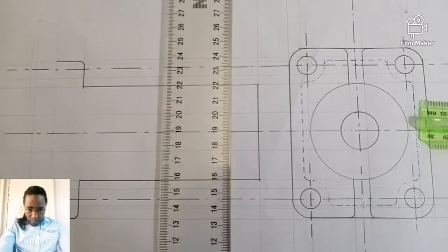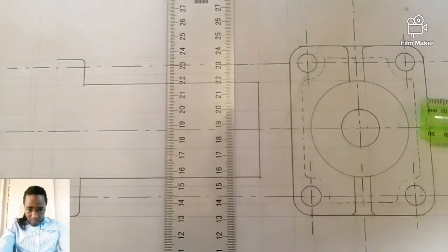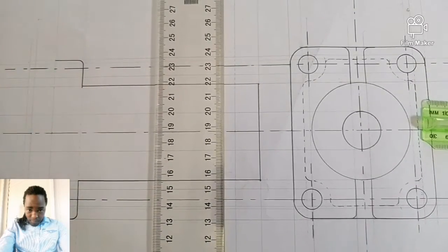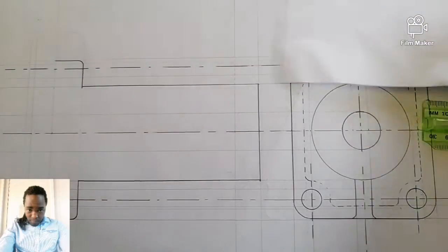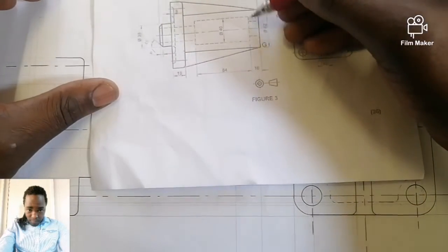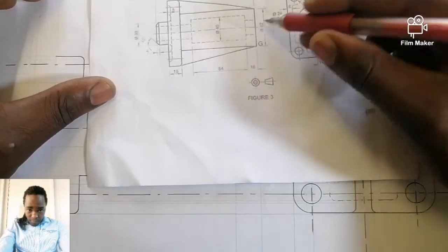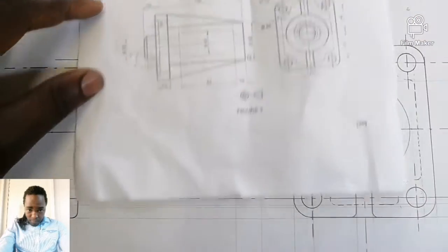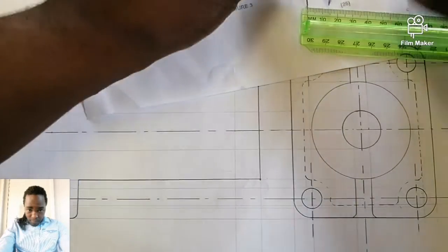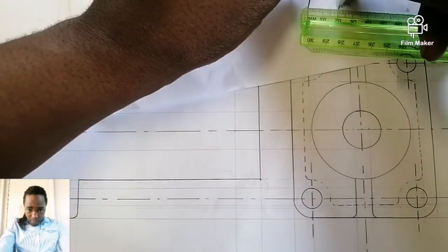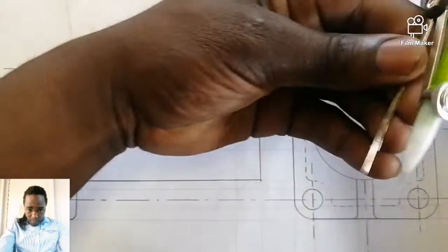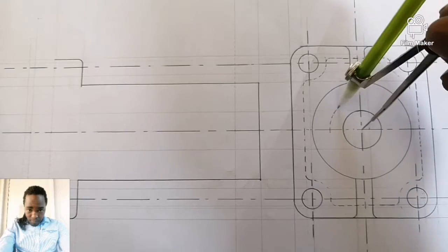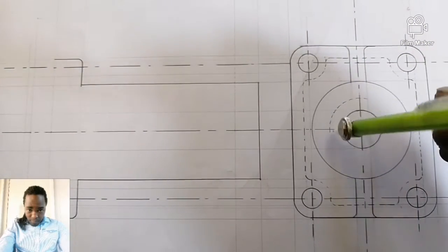So construct it up, because you are going to need it when you are drawing the third view, which is your top view. Are we together? So we are having a diameter of 40, and this 40 is one of these hidden details. So you better draw it. 40 divided by 2 is 20, isn't it? There it is. So draw it hidden like this.